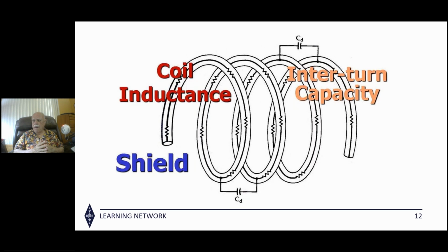Next, you mentioned to not use a balanced tuner, but what about a link coupled tuner that is truly balanced? That's fine. You'll find a lot of modern tuners fake a balanced output. And how do they fake a balanced output? They put a ferrite Balun inside the tuner, and it's usually a voltage Balun. I hate voltage Baluns because they have many nasty characteristics. I don't mind choke Baluns, which put stuff on the outside of the coax, but the typical voltage Balun can become very, very lossy if the impedances that you're trying to match in the antenna are high. So I generally tell people, if you've got a balanced output on your tuner, don't use it. Put a choke balun on the outside.